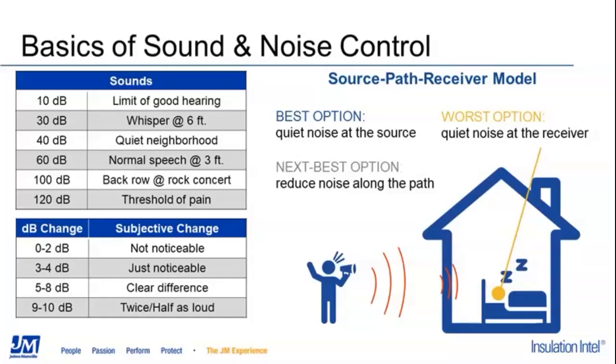But if you're not able to fix the noise at the source, maybe it's a renovation project where you have equipment you're planning to reuse, we can't do too much with the source in those cases. So here we can try to reduce the noise along the transmission path, possibly by improving the separation between the equipment and the receivers, or some kind of treatment along those paths.